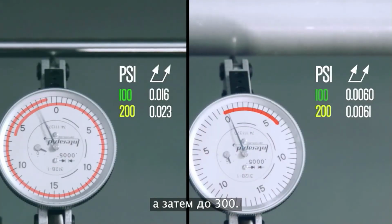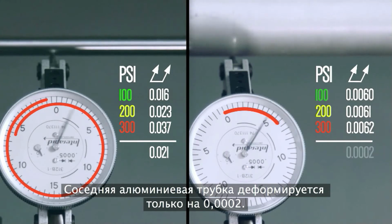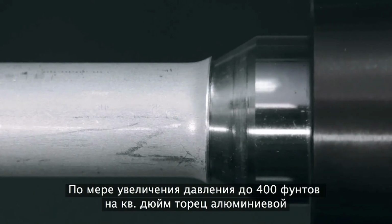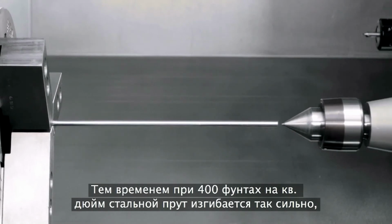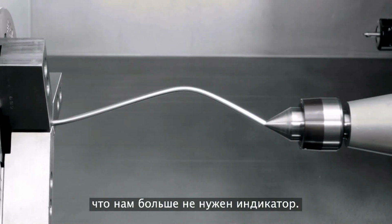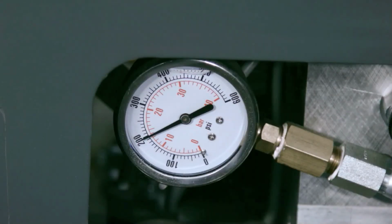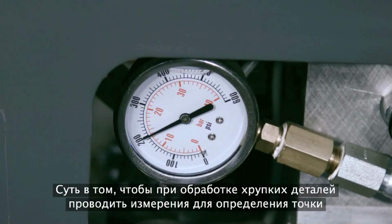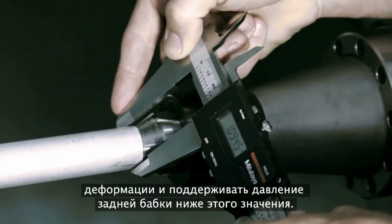and then 300, the steel rod deforms significantly by an additional 21 thou. Its neighbor, the aluminum tube, deforms by only 2/10. All the way up to 400 psi, the end of the aluminum tube permanently deforms. Meanwhile, at 400 psi, the steel rod bends so much we don't need an indicator anymore. Okay, so why did we show you this? We want you to realize that 200 psi will probably not work for some weaker parts. The point is, when your part is fragile, take some measurements to find where it starts to deform and keep your tailstock pressure below this point.